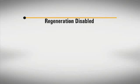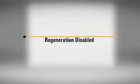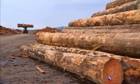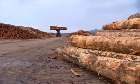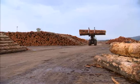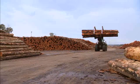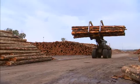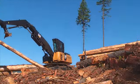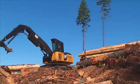Let's look at what happens when regeneration is disabled. The operator can disable regeneration using the manual disable switch, number 1, or disable button, number 2, in the cab. The regeneration status will appear as disabled in the display window. Why would we disable regeneration? We disable it if we're working in an application where there is flammable debris such as wood chips or dry forest conditions, or if there are gases, dust, or other risks that we need to avoid. So we disable regen, and when the machine is in a safe stationary setting, we manually initiate a regen cycle.